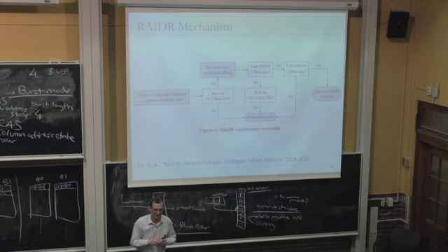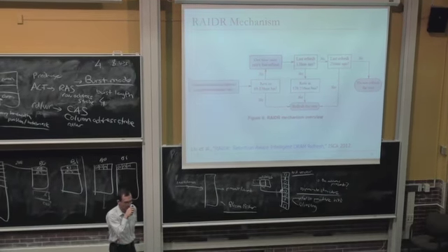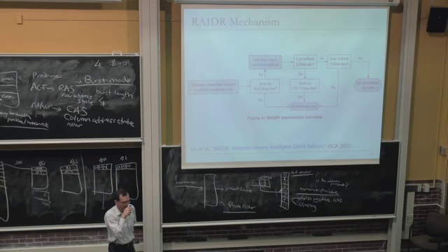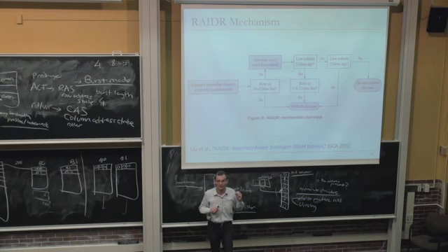Yes, you have a question? So is the idea that if there's some address that has that pattern of bits, then you must set the bit, otherwise it is clear? That's right. If there's some address that happens to map to a bit in the bit vector, and that needs to be refreshed within this interval, you set the bit. And if another address happens to map to that same bit, it'll use that bit to determine whether it needs to be refreshed or not.